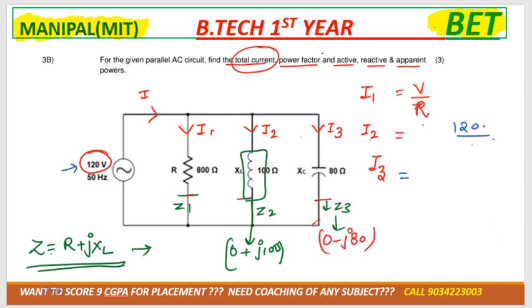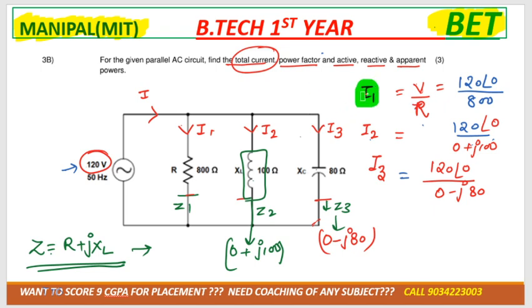So that would be 120 angle 0 divided by 0 plus j100. I3 would be how much? 120 angle 0 divided by, tell me, 120 angle 0 divided by minus j80. For this case, I1 is equal to 120 angle 0 divided by 800 ohm. This is I1, this is I2 and this is I3.